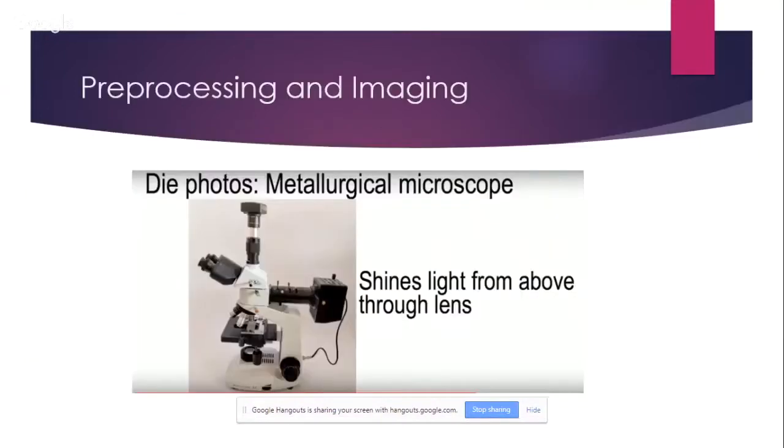So reverse engineering ICs actually starts in ways that are surprisingly similar to reverse engineering a preserved brain. First, chips need to be pre-processed to expose the layers to be imaged. This is analogous to plastination or aldehyde stabilized cryopreservation and slicing or ablation of thin layers of the brain. And once these important layers are exposed, the process continues with something called a die photo.